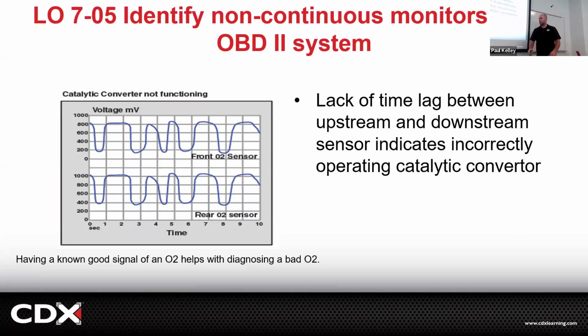The catalytic converter. Okay, so the OBD II system doesn't tell you that, right? That's another limitation of OBD. The OBD II system doesn't say P0420, but also you should probably check the front O2 sensor because it might have killed this cat, and that's why it set the P0420. It just sets the P0420, that's it. It's on you, the technician, to look at more cause and effect, like why did this situation occur? You want to know the most common one?